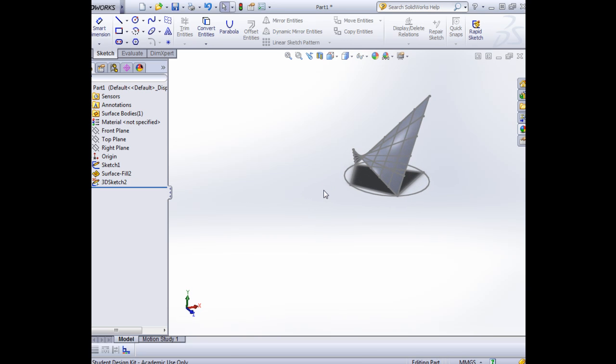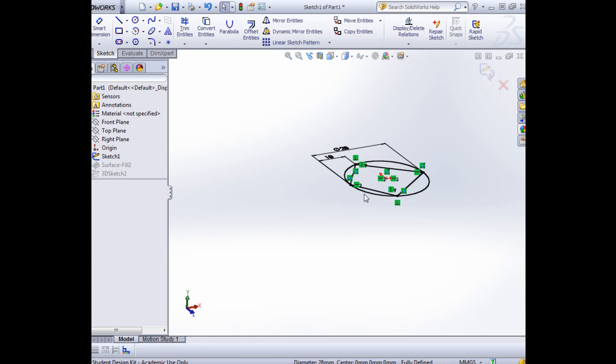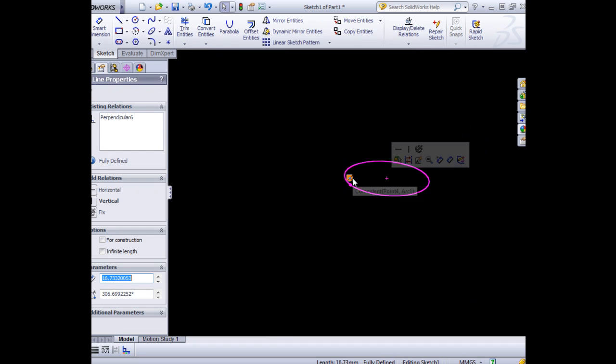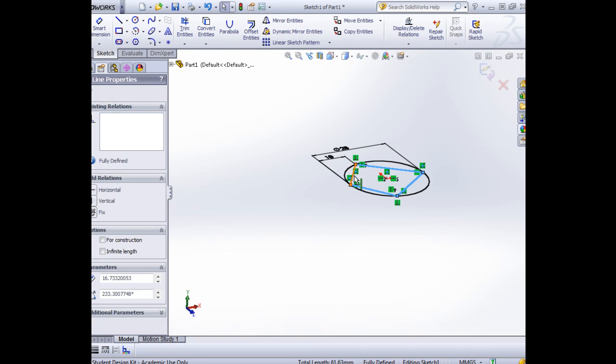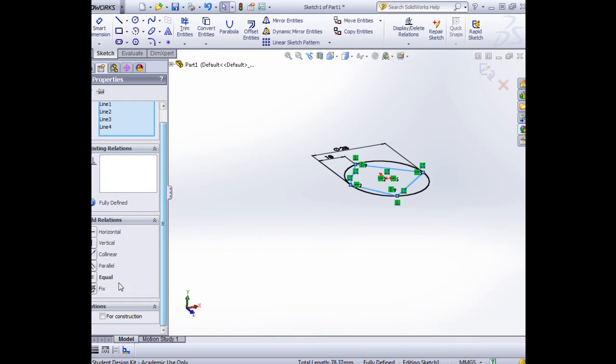The next thing I want to do is create this outer circle here. I want to create the boundary circle and extend on the original shape. So I'm just going to go into that sketch first of all, edit sketch, and make sure that these 4 lines here are all construction lines, so that I have nothing but construction lines.